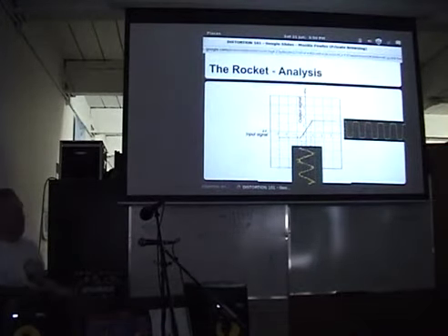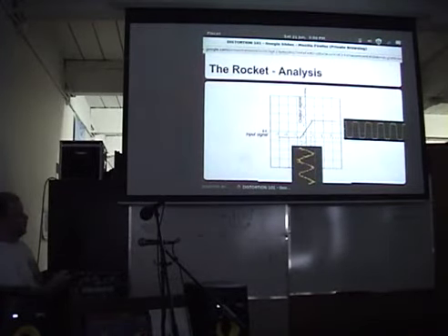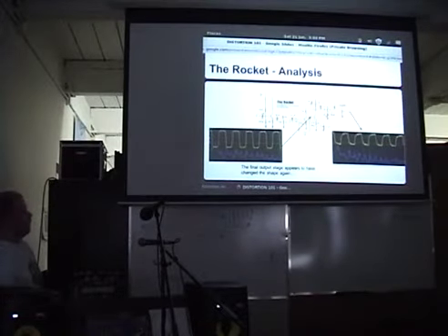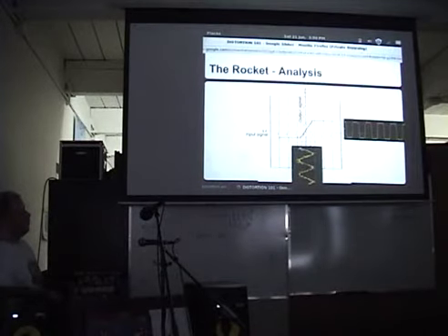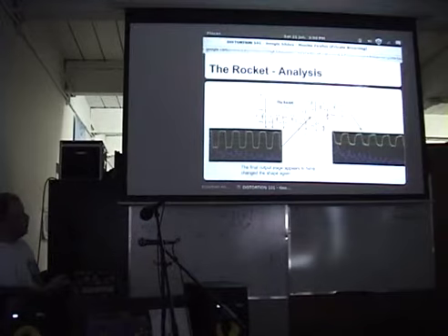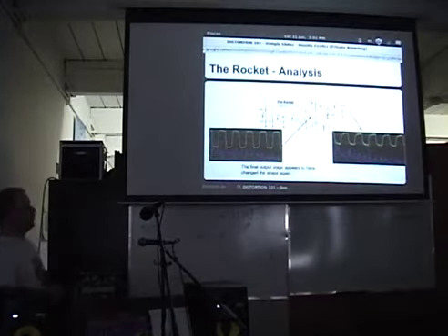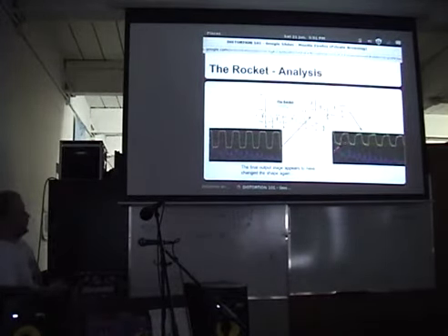So the transfer function might look a little something like this. There's the output of the input stage, and then it clips at these two maximum levels here. And then there's another amplification stage. By the way, this stage's gain factor would be about 100, so 10K divided by 100, whereas this one is closer to about 2. It's 1.2K plus 10K over 4.7K, which all balances out to about 2. But it's doing some more interesting things to the signal here.